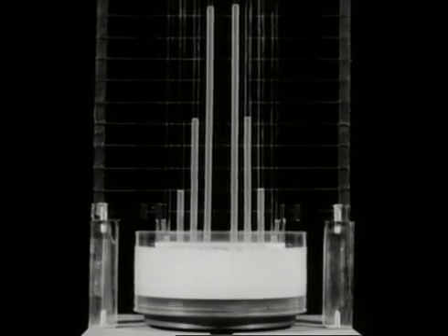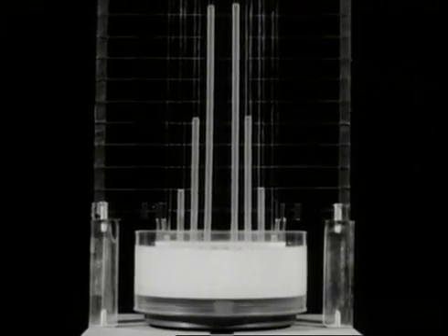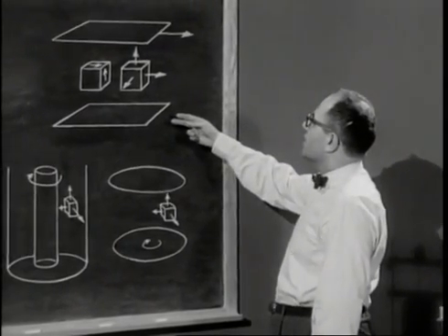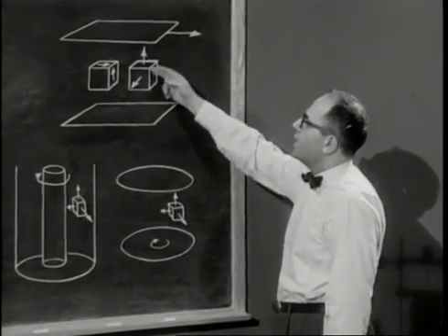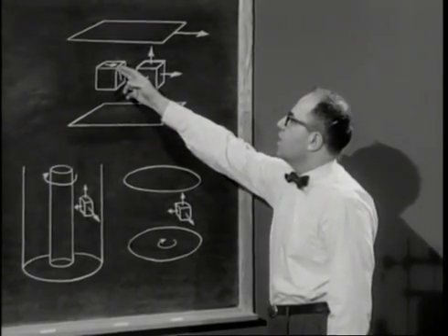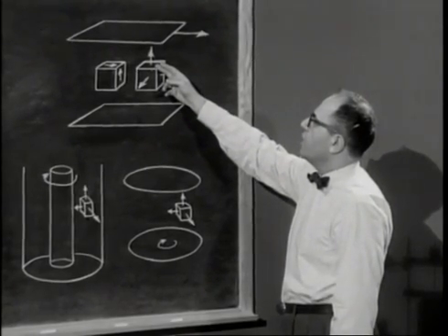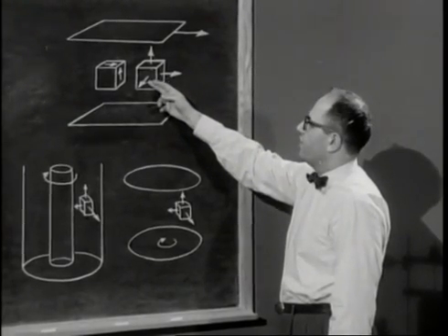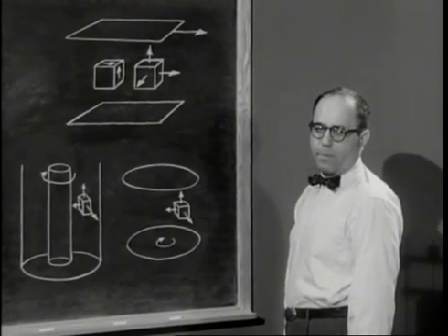These normal stress effects come directly from the nonlinearity in the stress deformation relation. This diagram represents steady, simple shearing between infinite parallel plates. In addition to the shear stresses, there are also normal stresses. For the Newtonian fluid, the normal stresses in these three directions are all the same. With nonlinearity in general, they will not be the same.